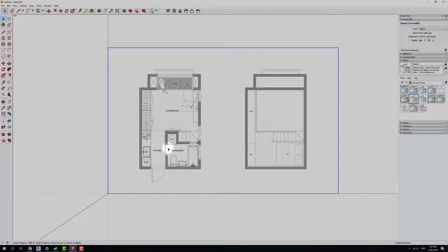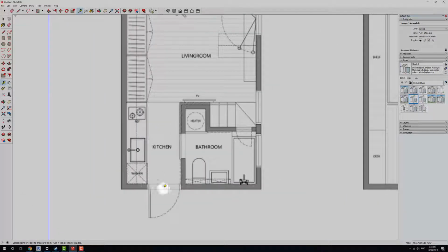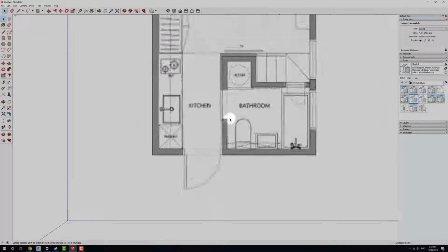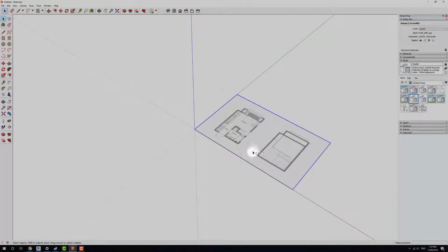The next tip I want to show you is the tape measure tool. Over here in our tape measure tool, we can do some funky stuff. If we know a rough dimension of something, let's say this door here is 1 meter wide, we can click once, and notice how we drag out, just like when modeling, and a length comes up over here. At the moment it is coming up 12,735 millimeters, so that's almost 13 meters. That's clearly wrong. There are two ways of going through this. I'll show you one way, and then I'll show you a quick tip.